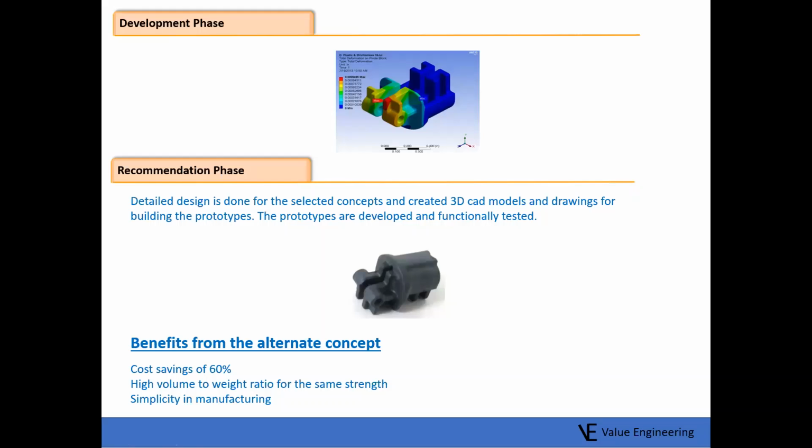we developed the prototype. Before doing the prototype, we did the FEA analysis to see the forces, because earlier it was done with stainless steel. So now we are going to plastic material, and we want to see what strength it can withstand. That is our concern, correct?